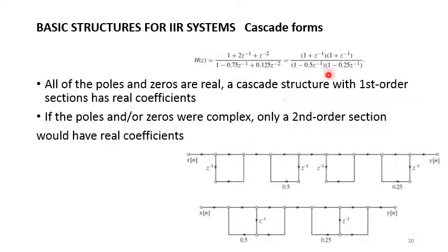Then we have the pole at 1 minus 0.5 z inverse, so we can write it like z inverse, and clearly you can see we'll scale it by a factor of 0.5, because of this minus in the formula. If we had 1 plus 0.5, then we'd write minus 0.5. So I hope this gives you understanding.